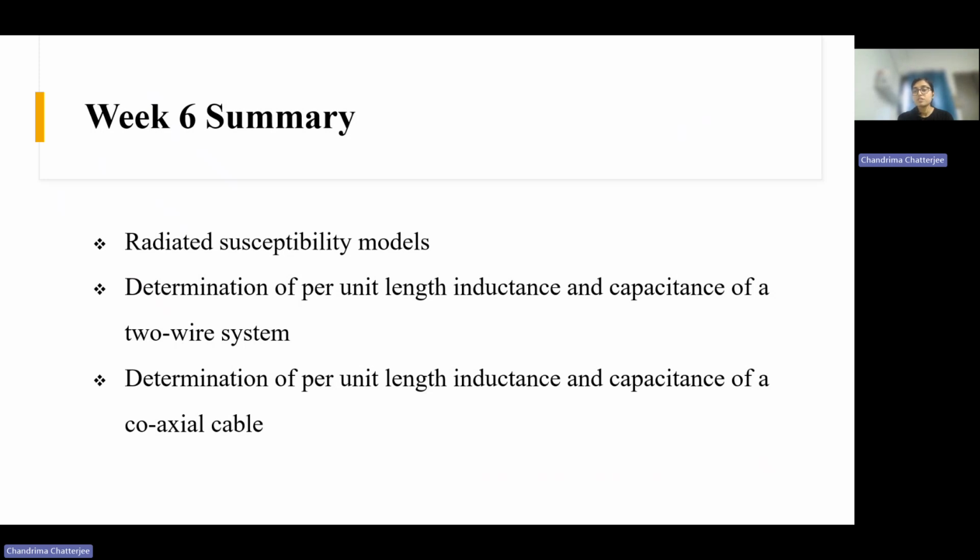For differential current, the current directions are opposite in the two wires. Therefore, the emission caused by differential mode currents is subtractive. But for common mode currents, the field is additive, so it is more detrimental.